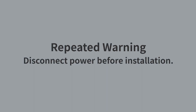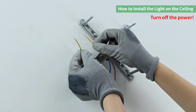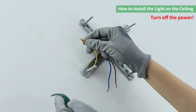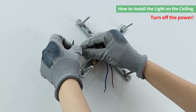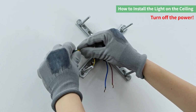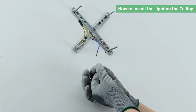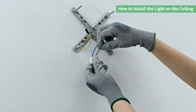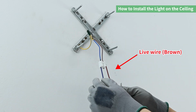Repeated warning: disconnect power before installation. Connect the ground wire using insulation tape to protect the circuit and prevent electrical leakage that could damage the light fixture. Without a ground wire, or if not connecting one, just the neutral and live wires will still allow the light fixture to function normally. Connect the indoor neutral and live wires to the corresponding neutral and live wires of the adapter through the terminal block. Alternatively, you can use insulation tape to connect the live and neutral wires. Pay attention to distinguish between live and neutral wires.